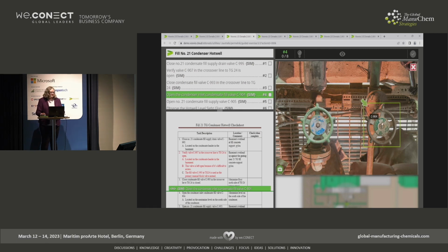It was a mistake that not only happened in the tool, but also was reflected in the field. And so they decided, as a measure, let's say, to exchange the hand wheel of one of the valves, put a bigger one, put a different color, to make it very obvious and prevent them from getting confused, and could eventually eliminate this source of mistake.